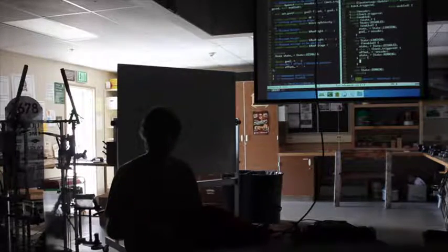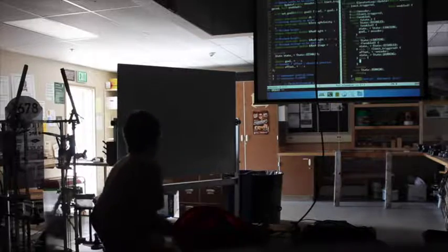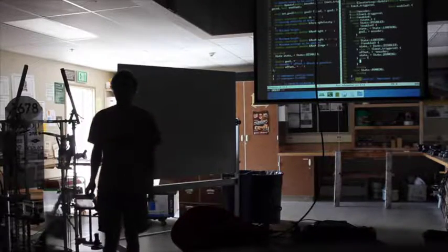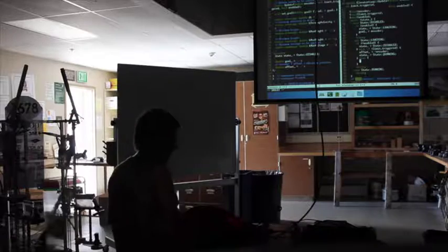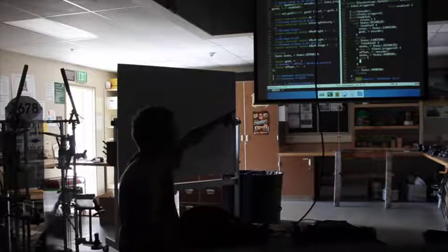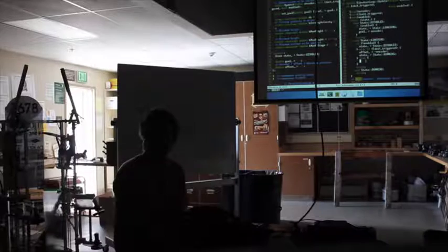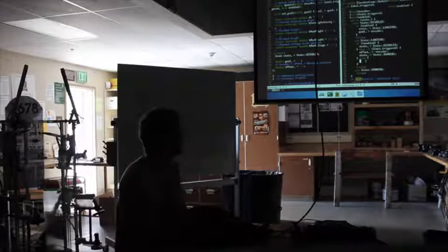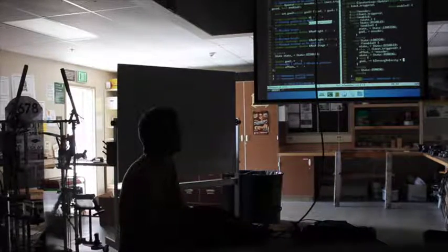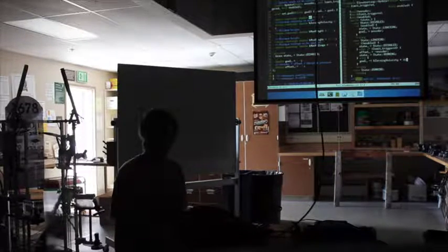Give the motor input at a certain voltage. But for our output, we want to let the control loop do that. We want to generate a goal here. So how do we generate a goal that moves down slowly? Whether or not it sees that value, like the Hall effect input. Sure, so that's deciding our edge transitions. But if we don't see it yet, we want to tell it to go down a little bit. So that's going to be an if. Yeah, if it doesn't see the Hall effect, keep going. And how do we keep going? Goal minus equals steering velocity times dt. Does that make sense?